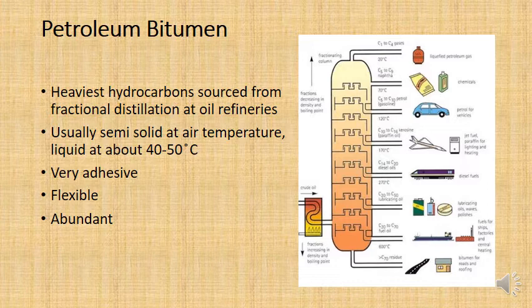And basically the highest ones are the highest quality hydrocarbons, and they're the cleanest burning and the most expensive. And the ones at the real bottom are the really long hydrocarbon chains, and they're the real thick, viscous chains. So you can see here that when the hydrocarbon has only 1 to 4 carbons, so anything from methane, ethane, propane and butane, that's a gas and that comes out right at the top. Now, what do we use that for? We use that for LPG bottles, for the gas for your oven.